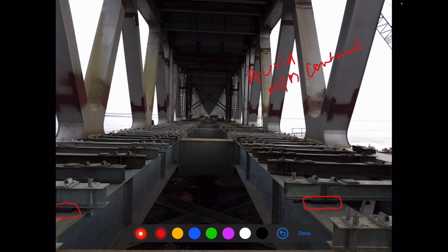When a train runs over these sleepers, due to the impact load, the sleepers will finally damage the top flange of the stringer and vice versa. So to have a cushioning effect, we put small rubber pads in between the steel sleeper and the top flange of the stringer. If you look carefully, you can also see the cross girders. These are the cross girders.